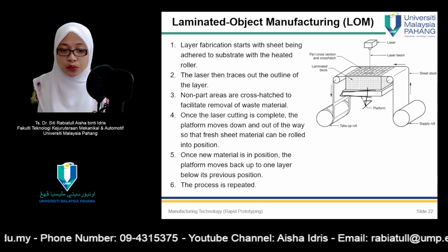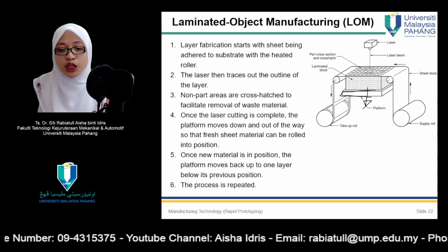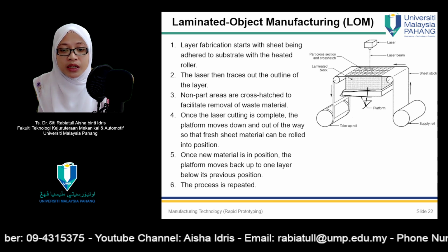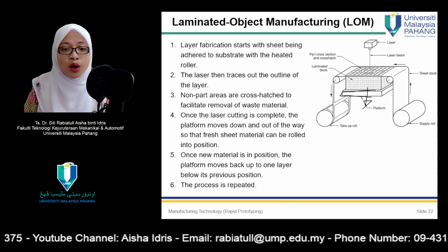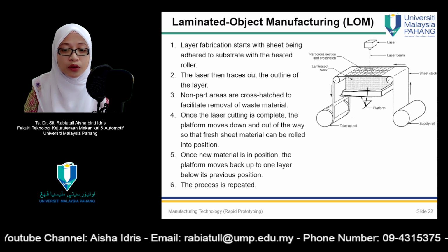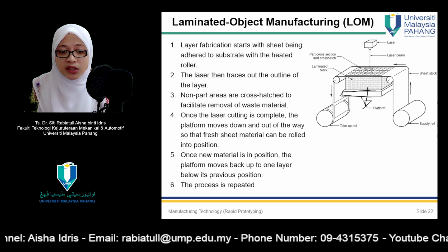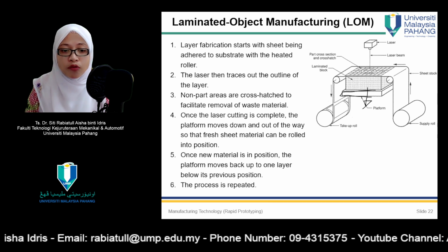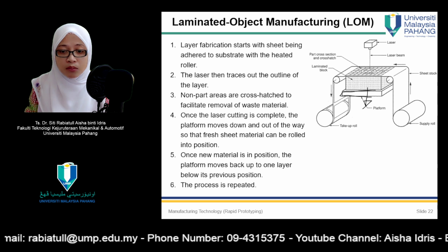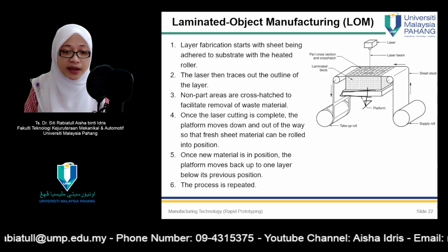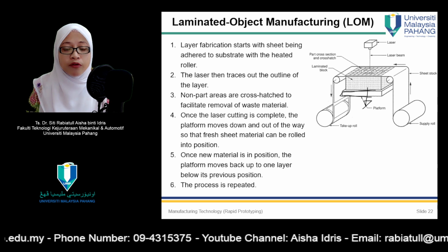With reference to this figure on your right hand side, the LOM process for each layer can be described as follows, starting with a section with a sheet of stock in place and bonded to the previous layer. Number 1, LOM Slice, which is the software, computes the cross-sectional perimeter for the STL model based on the measured height of the physical part at the current layer of completion.